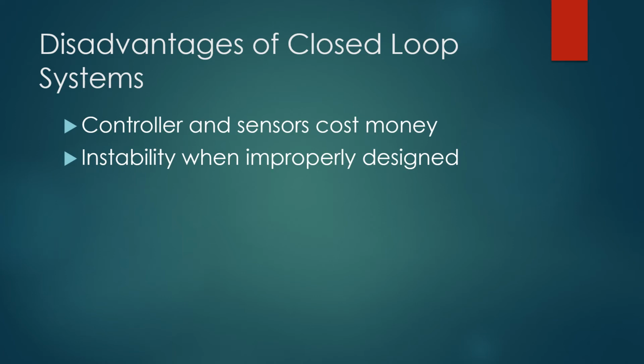Sometimes when it compensates, it overshoots its desired output, and then it compensates again. Depending on the design, it could overshoot infinitely, or in worst cases cause great instability, as the second overshoot could be greater than the first overshoot, giving rise to a very unstable system.